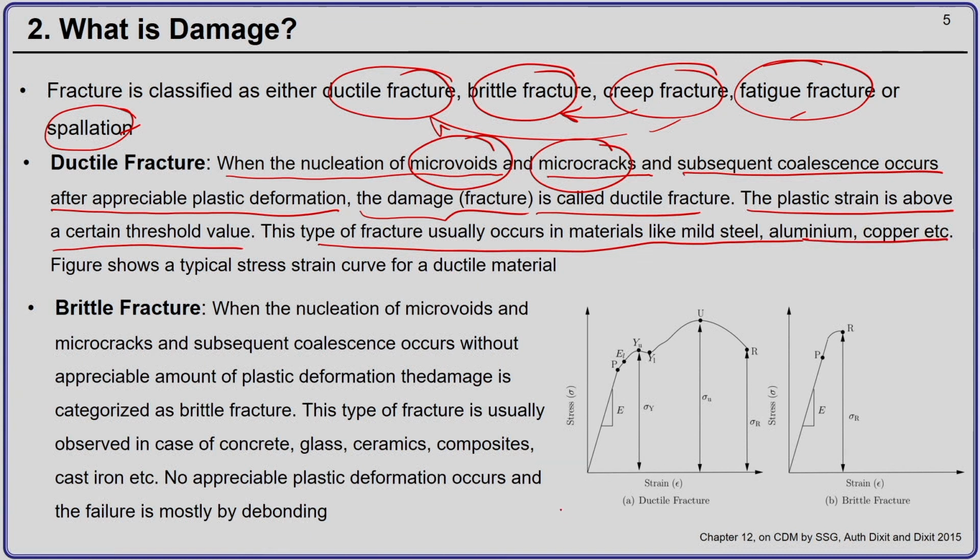Okay. So, this figure over here shows the stress strain graph of a typical ductile material. When you load a ductile material, it deforms elastically till a certain point called the proportional limit, after which it reaches the elastic limit, and then at this point the material yields. This is called the upper yield limit and there is a lower yield limit, and if you keep on applying the load, the stress again increases until it reaches a maximum point called the ultimate stress,